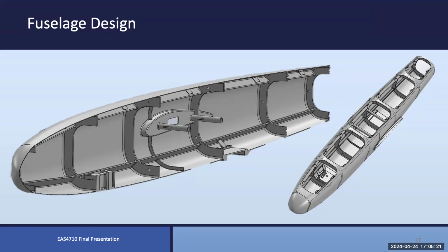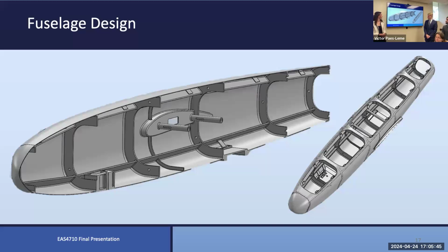What concerns me about that particular arrangement is you're sort of punching into your stringer, and there's not really a good load path to react that. Punching into the frame is a better solution than punching into the stringer like that. But clearly it worked, right? You guys were able to successfully land, and it didn't seem like that was a weak part of your design. So honestly, in future iterations, something we could do there is add another one of these mini frames around that back area. Yeah, that might be the right way to go. Thank you. Yep, that's all I got. Yeah, thank you, Tom.